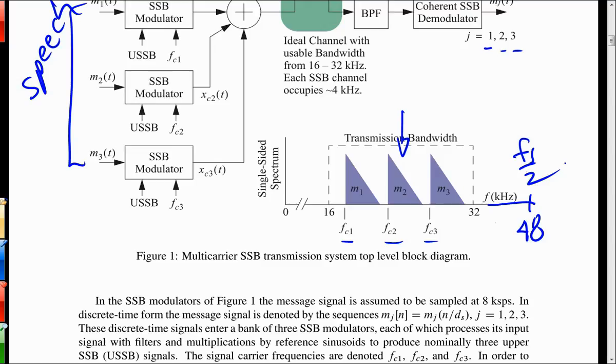Okay. But you can't leave it at the high sampling rate because it won't play back. In MATLAB, the codec in your computer might handle 96K, but it's throwing out lots of samples per second that are unnecessary for a message that only has a 4 kilohertz bandwidth, so you downsample it and then send it out.